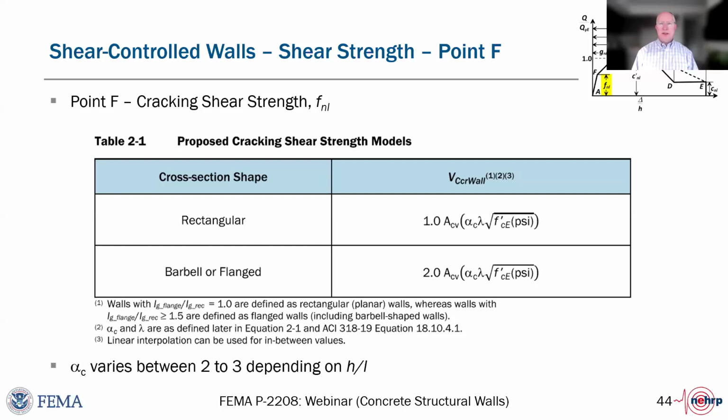Okay, and the corollary to that is if the lap splice does not meet ld, would you consider the wall to be non-conforming? Yeah, so that was the thing that I tried to highlight a little bit, is that it wouldn't mean that it's a non-conforming wall in terms of using that table. It means it's definitely not a conforming wall. You can't use the conforming table, but you still have to consider those overarching provisions that happen. Those govern the overall standard. They're not just relevant to walls. There are provisions in there for adequate or inadequate laps that govern everything.